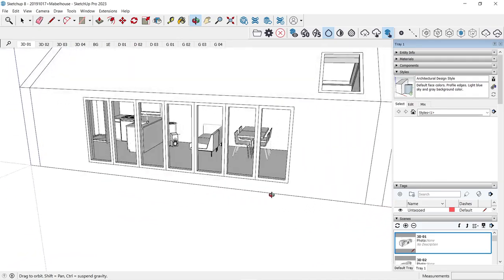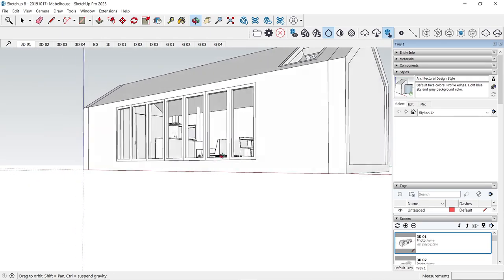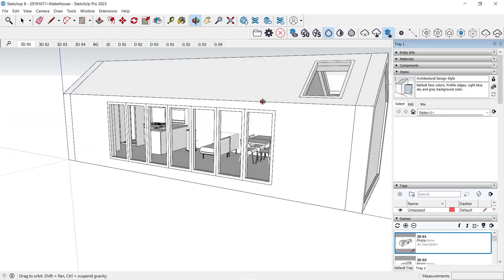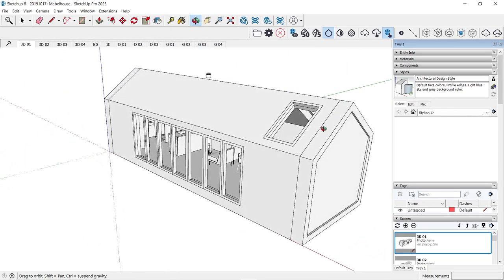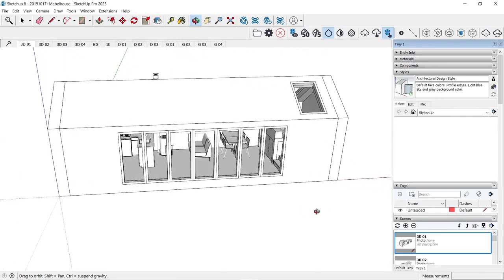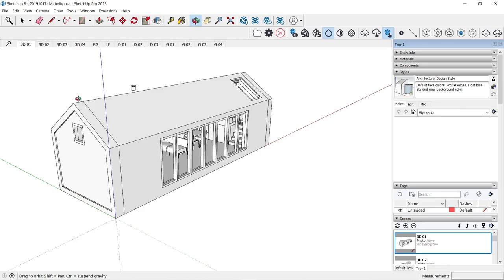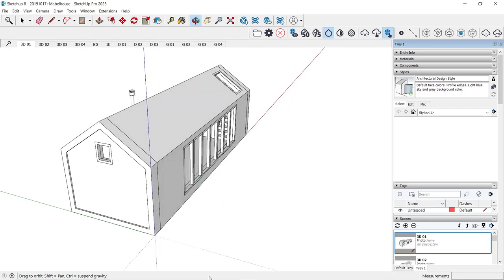Now, I'm a civil engineer by profession, so it helps to know how this building is able to stand. That's what I'm thinking about, how the roof is able to stand without structural elements in the center. So that just means that to some extent the walls of the building are structural walls or load-bearing walls. That's my assumption, and if not all of them are structural bearing walls, then at least two of them are structural or load-bearing walls. So we'll just head into Revit now.